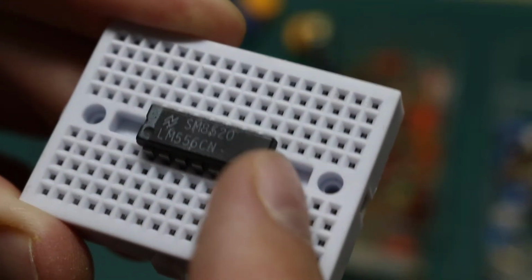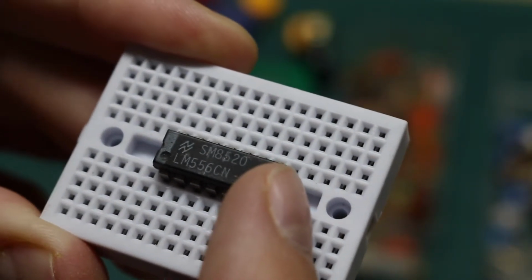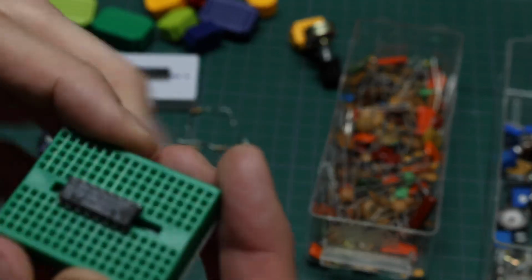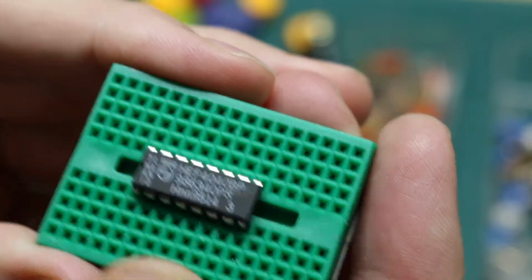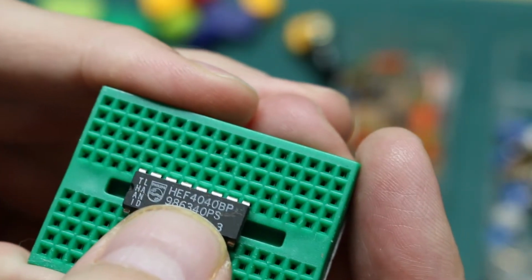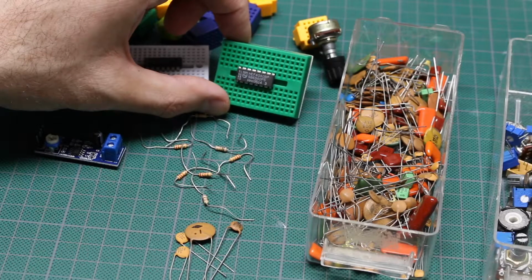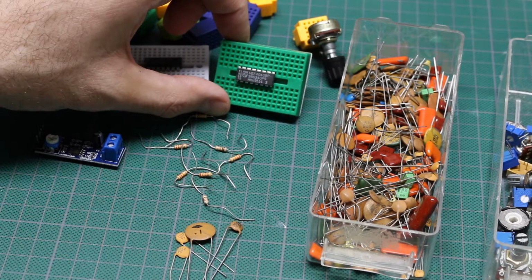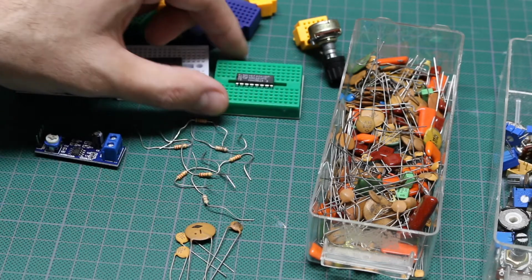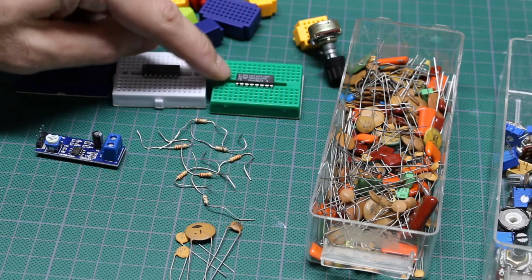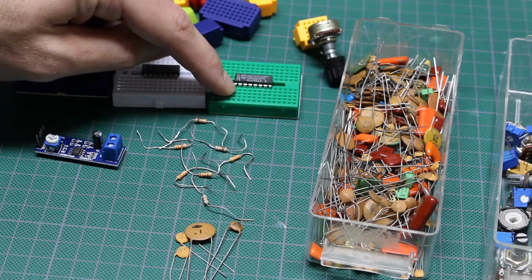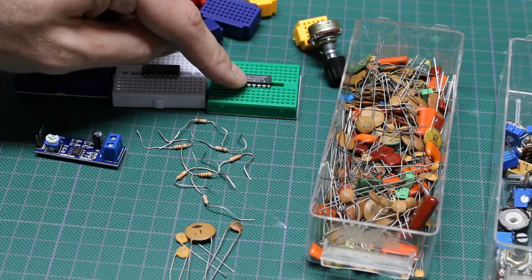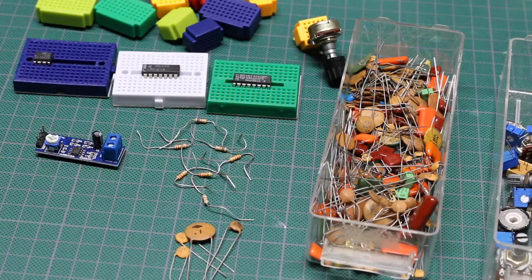I've had this chip a very long time, probably since the 80s. Now this is the major change I'm going to try for this experiment compared to the LTSpice simulation. I happen to have a 4040 chip. This is like having 12 stages of flip-flops chained up in a row. So all I got to do is send the 555 clock in, and then I just have 12 individual outputs that each are going to be half of the previous flip-flop's frequency. So I'm going to go and try to build some of this and see if I can get it working.